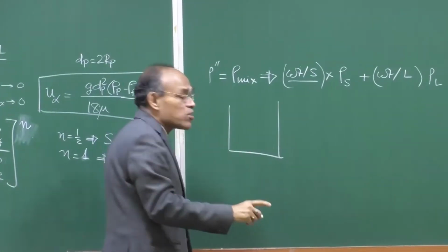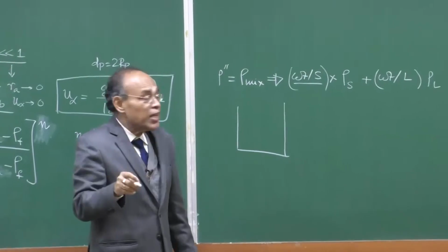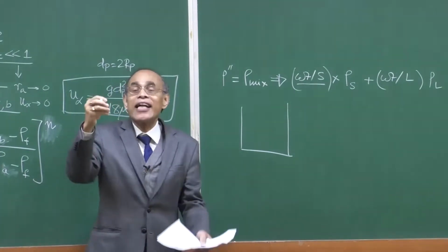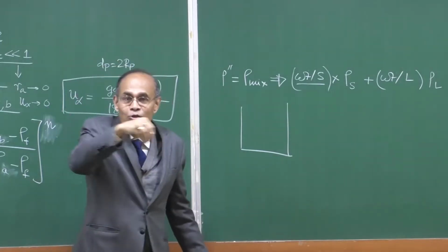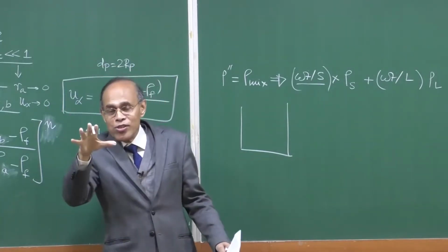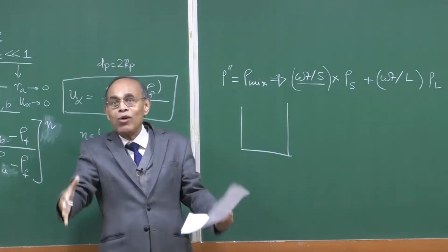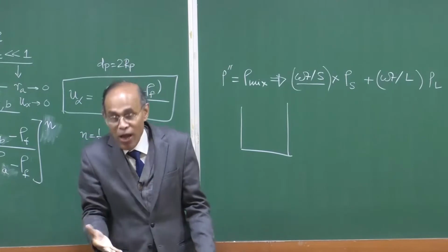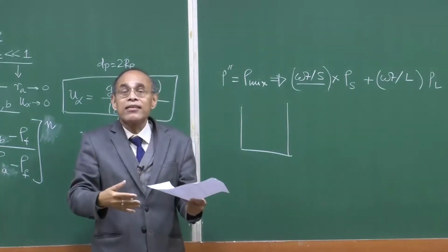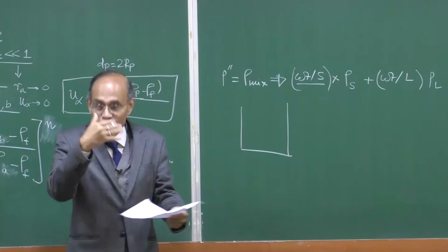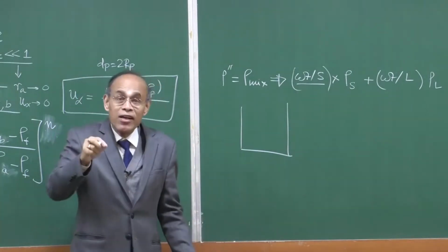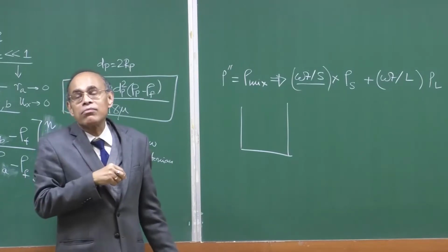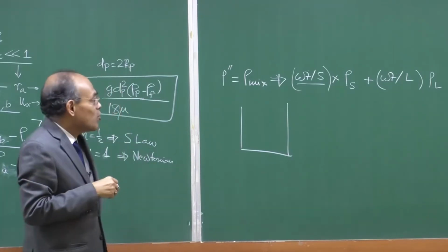So, in the context of a galena-quartz mixture, if I tell you that the quartz is in suspension, you can imagine that the galena particle settling would be colliding. It is not a pure scenario of clear water. No, there are suspended particles of quartz. As a result, we have to consider the effective density, or the solid-liquid mixture density, to find out how much time the galena particle would take to settle down through that mixture in the system.